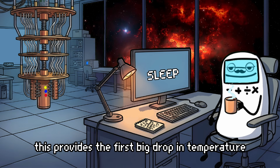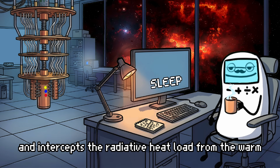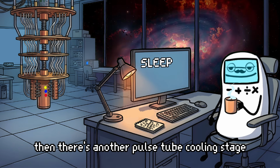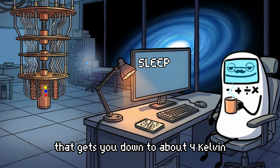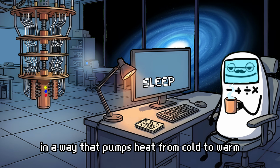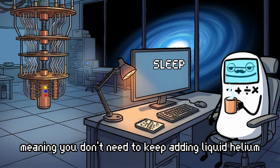This provides the first big drop in temperature and intercepts the radiative heat load from the warm outer walls. Then there's another pulse tube cooling stage that gets you down to about 4 Kelvin. These pulse tubes work by compressing and expanding helium gas in a way that pumps heat from cold to warm, and they're closed cycle systems, meaning you don't need to keep adding liquid helium.